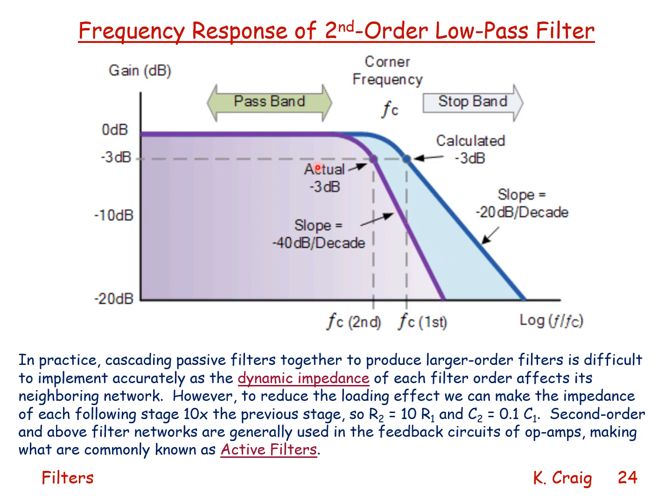And we see that the breakpoints, the frequency at which the amplitude ratio drops minus 3 dB, or 0.707 of the low frequency value, which is 0 dB or 1, because we can't have amplification here. And we see that that breakpoint is different. And we notice that in our two experimental plots from the myDAQ. We notice that difference.